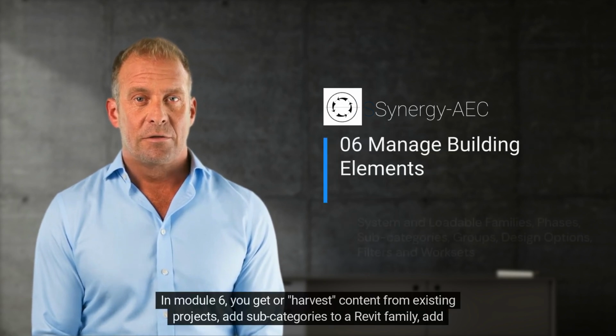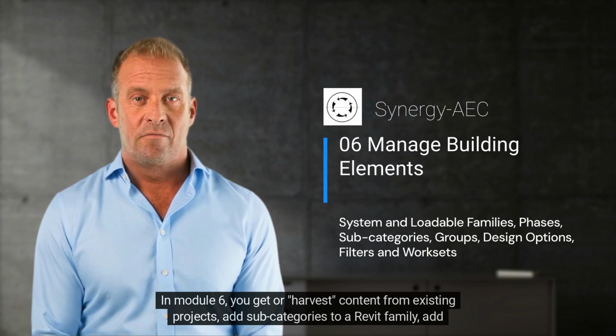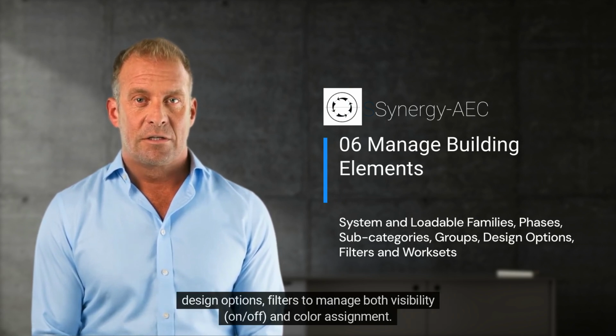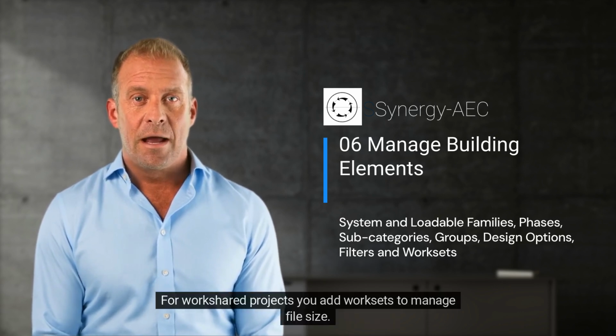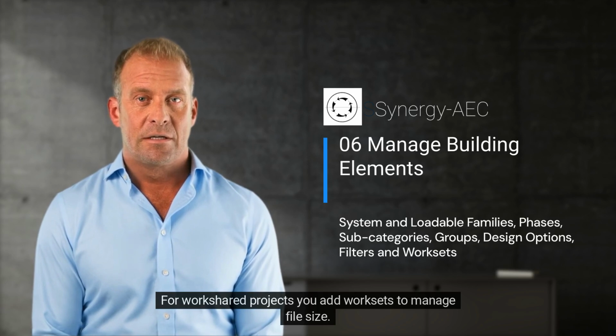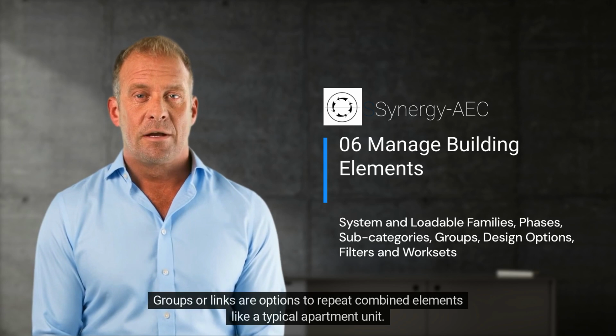In Module 6, you get or harvest content from existing projects, add subcategories to a Revit family, add design options, filters to manage both visibility, on, off, and color assignment. For work-shared projects, you add work sets to manage file size. Groups or links are options to repeat combined elements like a typical apartment unit.